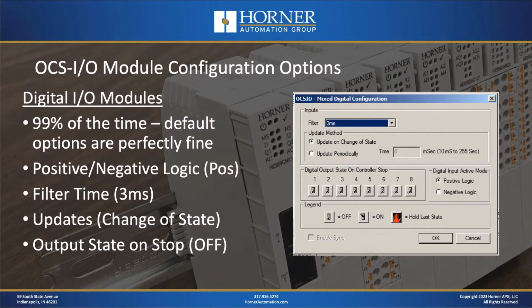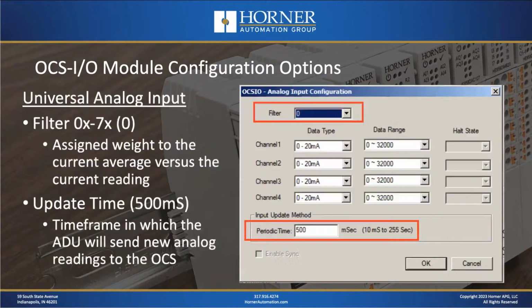Now, the one thing you might change occasionally would be if you ever need to configure the I/O points for negative logic instead of positive logic, then you would go into the configuration for that particular module and change the input configuration from positive logic to negative logic. But that's the exception. 99% of other cases, you're just going to leave it at default.